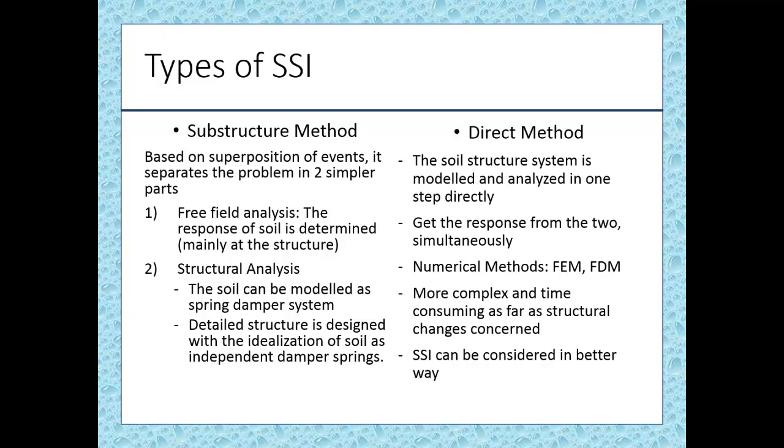The soil dynamic stiffness coefficients can then be simulated as a spring damper system in the structural software, and this particular thing corresponds to the evaluation of a kinematic effect. The second step is the structure supported by the spring damper system. It is analyzed by the load case that depends on the free field movement. This step is a short interaction, hence the mass of the structure and the foundation is considered.